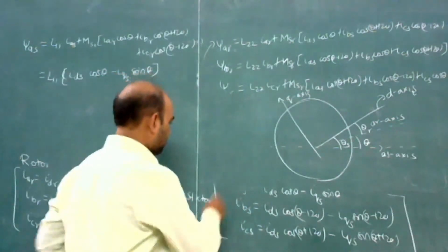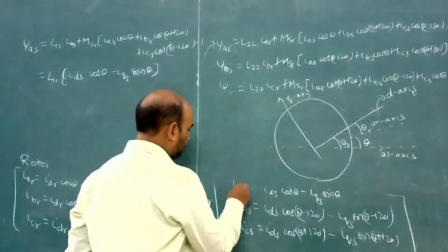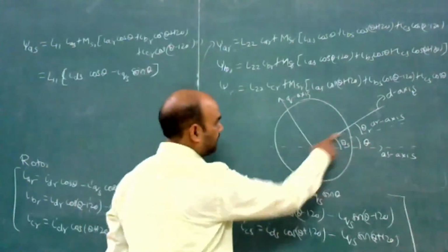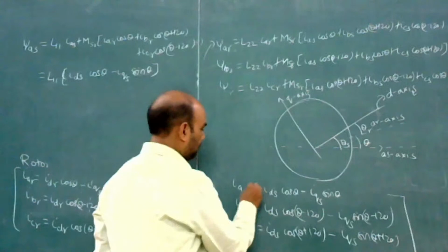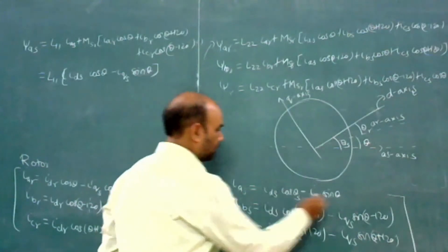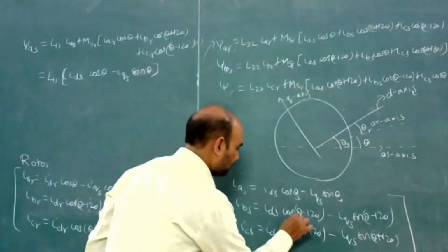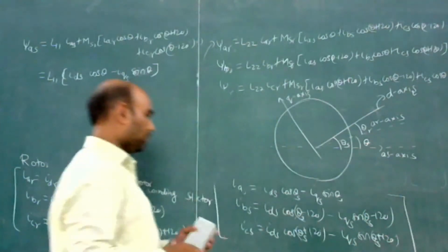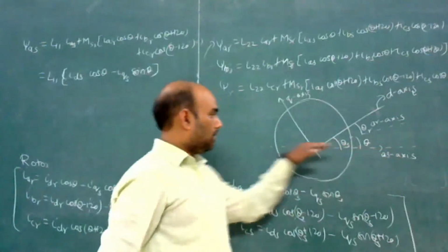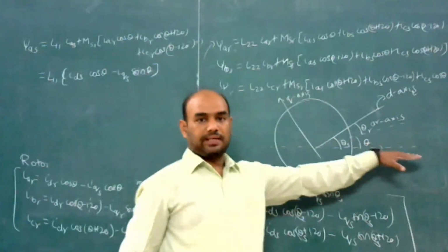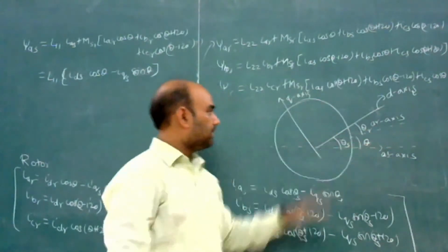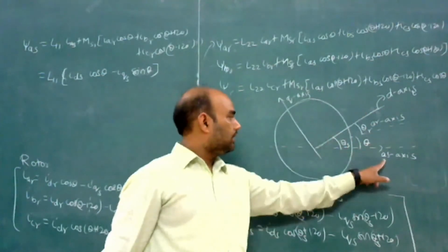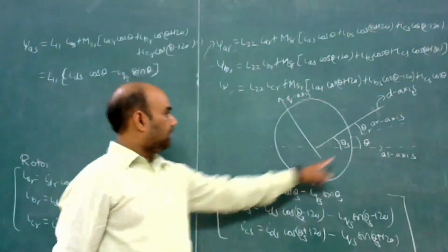So this is the transformation of the stator to the D axis. The angle between the D axis and the stator phase axis is theta s.